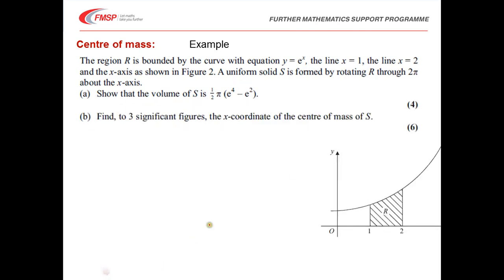So far so good. Okay, onwards then, we're going to take a look at finding the x-coordinate of the centre of mass of S. Again, if you're wanting to work through this, now's a good time to pause. We're going to again think about our element. So the moment of our element, remember we were saying we needed to sum all the individual moments. So the moment of the element about the y-axis. Because we're looking for an x-coordinate of the centre of mass, we want to take moments about the y-axis.